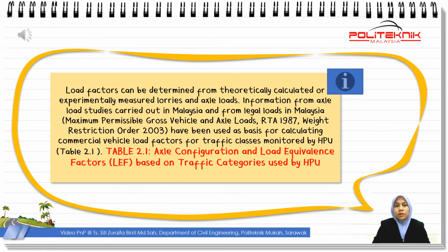For your information, load factor can be determined from theoretically calculated or experimentally measured lorry and axle load. Information from axle load study carried out in Malaysia and from legal load in Malaysia has been used as basis for calculating commercial vehicle load factor for traffic classes monitored by HPU. By using Table 2.1, there is axle configuration and load equivalent factor LEF based on traffic category used by HPU.